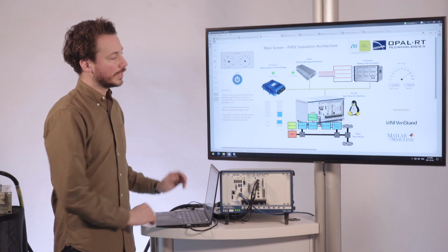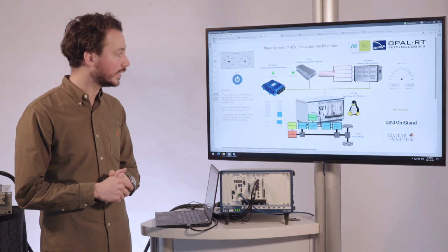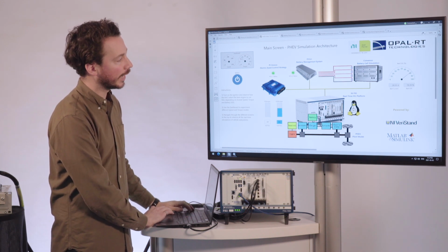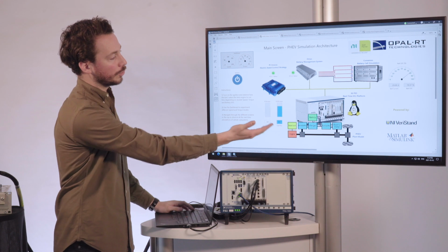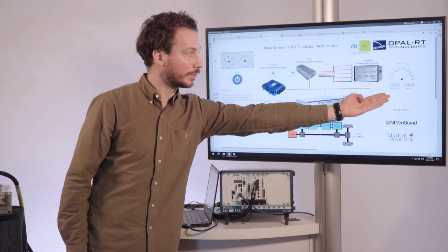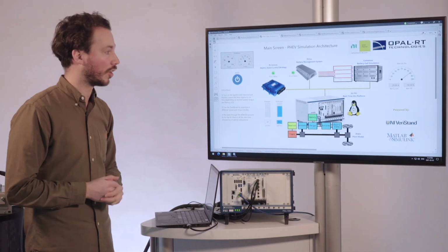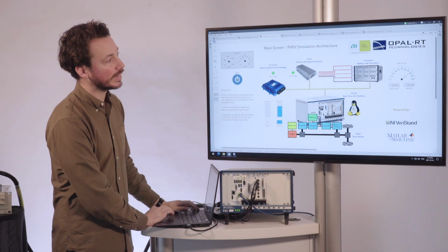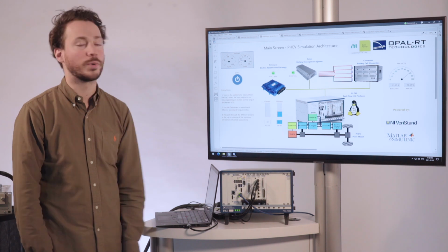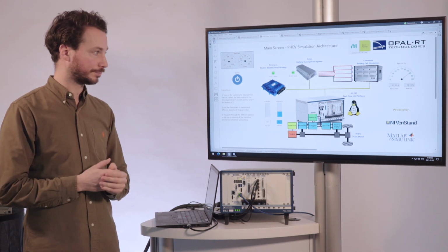If I increase the speed, and I give it a little bit of torque, we can see here this tank is basically showing the amount of torque that our electric machine is providing. And as we increase the torque, we can see our torque meter going up. What we'd also notice is that our battery current, which is shown here, is going to be draining more power from the battery pack as our torque increases. Right now, for example, we're at around 30 amps. If I decrease the torque, it's dropping down to about 23 amps. And all of that is coming from, again, the simulated model of the cells.